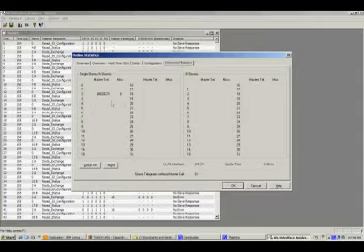And then on advanced diagnostics here, I'm monitoring the number of messages that have been sent. Now notice that there are no missed messages at this time. So if I go jiggle or loosen the connection here to this particular node, as such, you'll see that I can generate a number of missed packages there. So if I go ahead and just take it on and off real quick again as well, you'll see there that I've got missed packages, missed messages also occurring.